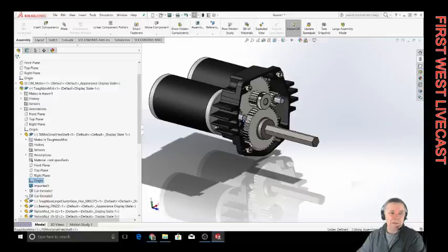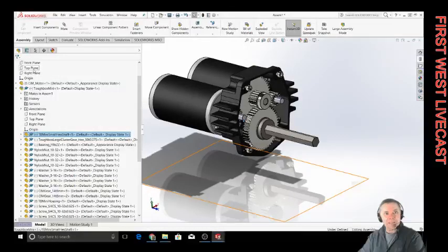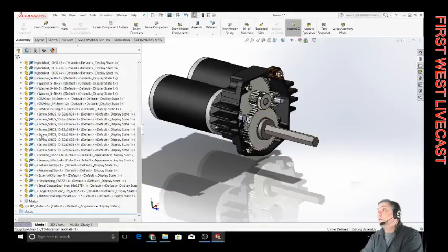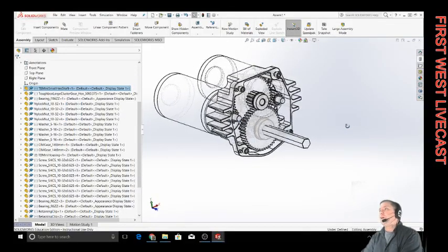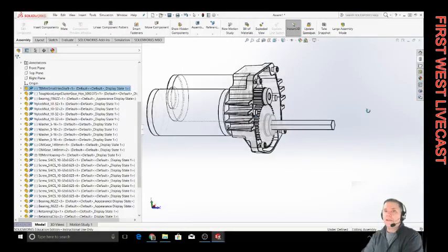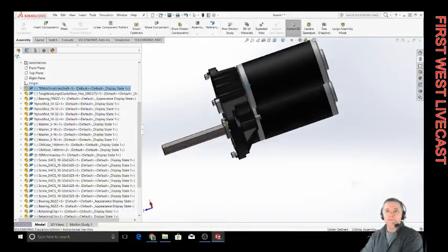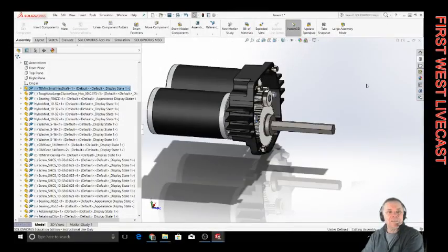All right. This parametric table on the side, this features table, gets to be pretty large after a while. Now, if you find that your system starts to bog down, like mine did, you can actually switch over to wireframe, like this, and that takes a lot less processing. Work moves a lot faster, and then bring it into a solid model when you're actually ready to look at it in all of its awe and beauty.